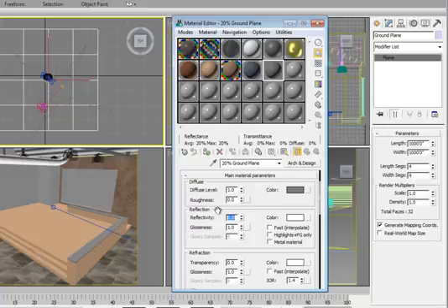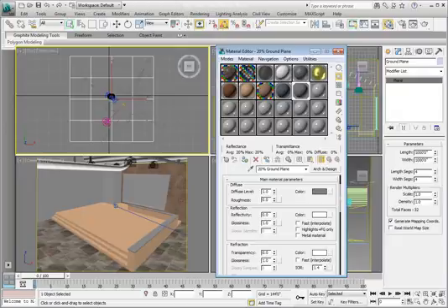In the Material Editor lower toolbar, click Assign Material to Selection, the third button from the left. Notice the highlighted corners of the material sample slot. From the 3ds Max application button, click Save As. Click Increment on Save to name the file Chapter 16 Office Suite Materials 02.